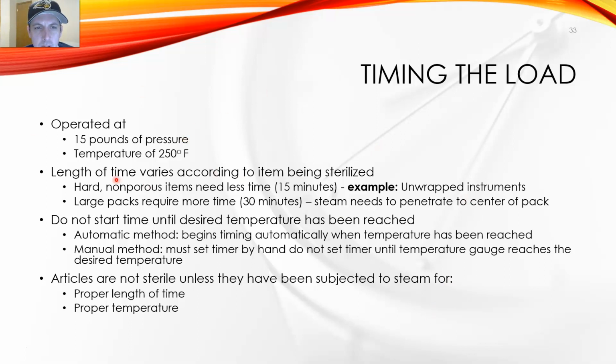As far as timing the load, like we said, most of the time it's operated at 15 pounds of pressure, 250 degrees. Automatic ones will simply do all of this on their own. More of a concern are the manual ones. Once it reaches the temperature, you can go ahead and set the timer.